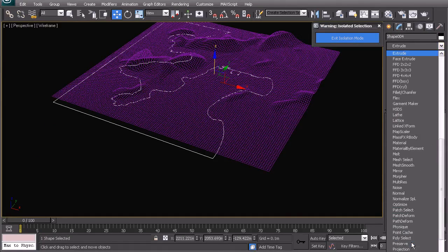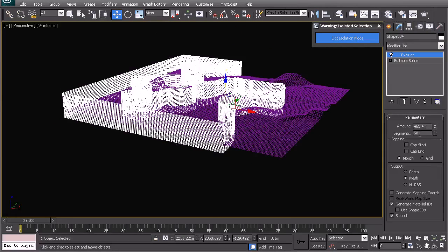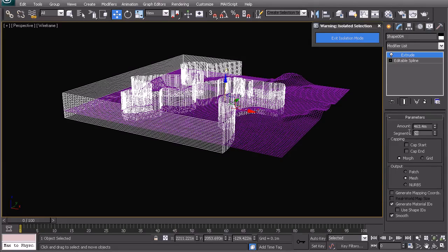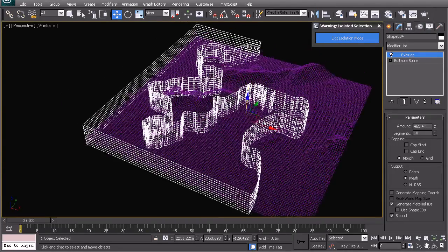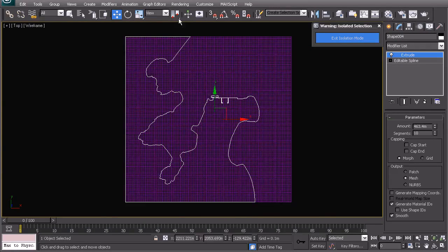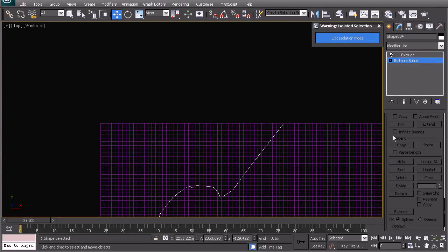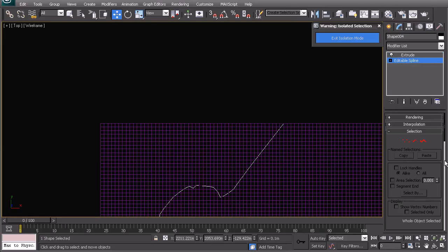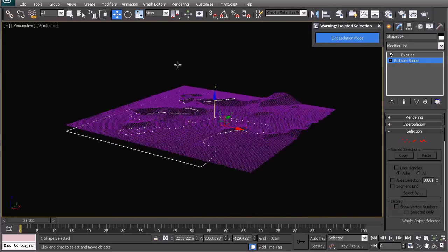We're going to extrude that. And as I've extruded it, I've just left a couple of segments in it. We don't need 50, we can use slightly less. Sometimes you really don't need to do it. It does help. Maybe 10 is good enough. And in our top view, we can just check that it's out. I mean, generally it helps if this part is actually outside. Just don't want to make it less accurate by shifting too many things around. So let's just give it a go like it is and see if it works.